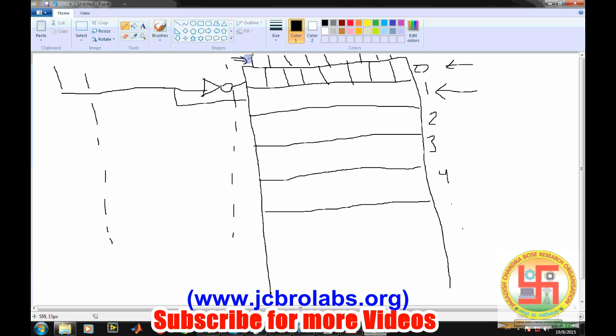If we want to write, whatever data is present on the data bus will be written inside the memory location. Now from a single wire, it is clear we can access only 2 addresses, because it has only 2 states, either 0 or 1. So if we have 2 wires, the total combinations which can go on these 2 wires are 4: 0 0, 0 1, 1 0 and 1 1.